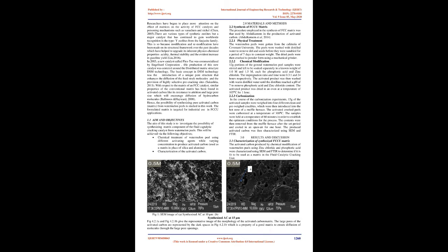Zeolites are hydrated aluminosilicate materials made from interlinked tetrahedra of alumina, AlO4, and silica, SiO4. 130 out of 840 catalysts used in industrial applications are based on zeolites, and the FCCU in petroleum refineries utilizes over 61% of these zeolite-based catalysts (Oil and Gas Journal, 2003; Elehinafe et al., 2019). The pore distribution, acidic properties, high selectivity, and thermal stability of zeolite catalysts make them stand out amongst other non-zeolite catalysts in the FCCU due to the significant increase in gasoline yield and octane number boost.